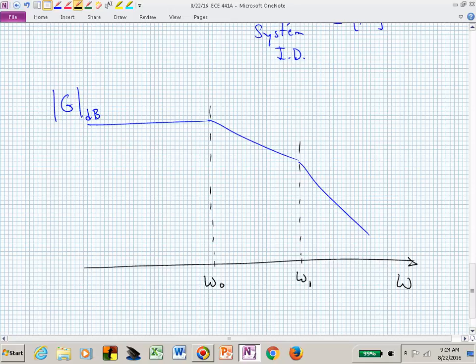What do we have with respect to a transfer function? Just pick a transfer function and just write it down on paper. And what do you see? There's some numbers, there's some different factors, aren't there? There's factors in the numerator, there's factors in the denominator. Those might have particular descriptions. Poles and zeros. Yay! Which is which? Where are your poles? In the denominator. They're downstairs, and when those factors go to 0, your whole transfer function goes to infinity. That's why it's called a pole.